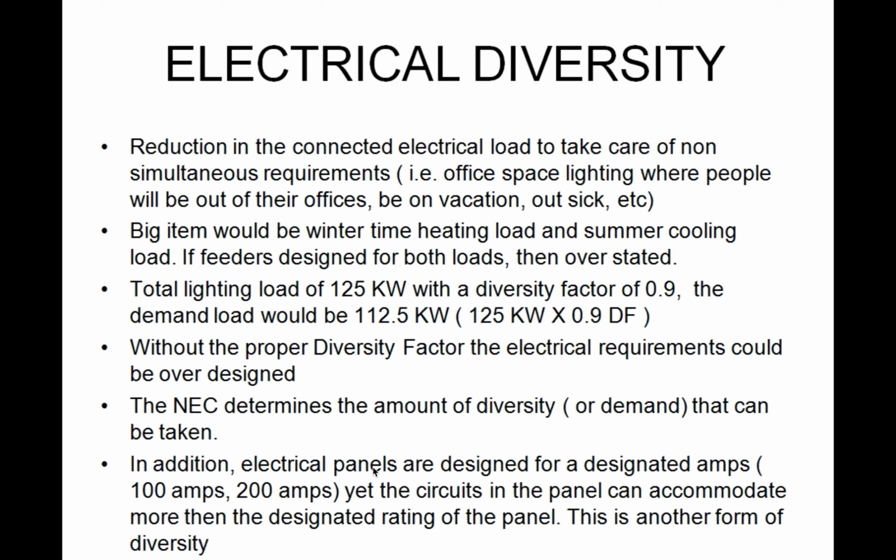In the example here in bullet number 3, 125 kilowatts would be the total load if everything was turned on at all times, and we can safely say that 90% of that load is accurate as your peak load. Devices can be expensive, so we don't want to always plan for the worst case scenario when we know that's not going to happen.